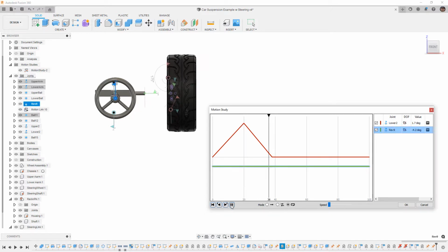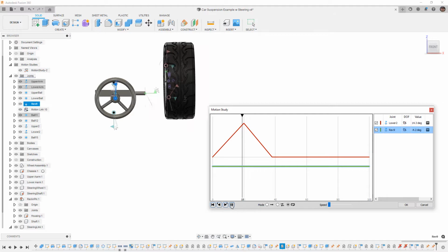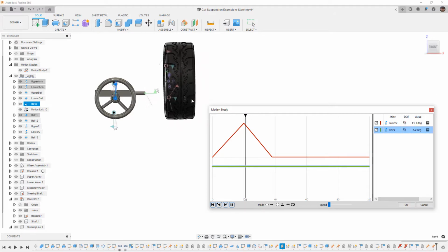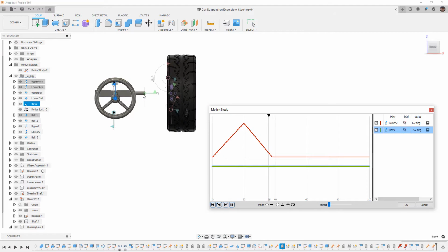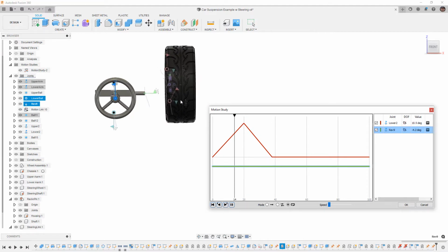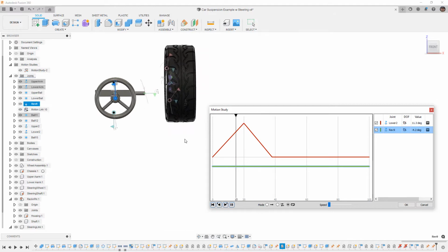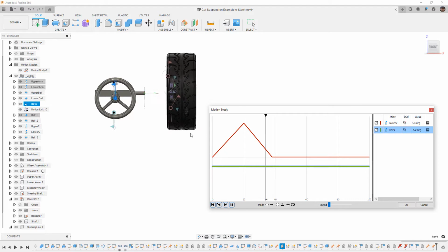Now that it's completely at 0, it looks like it's moving just a little bit still, but you can see here that now we're getting a little bit of toe out, which means that we need to make some additional adjustments because we certainly don't want it to go toe out when we're compressing the suspension, because that's going to cause an instability. Now, if it's the rear, then that's okay. If it's the front, then we kind of want it to toe in a little bit.